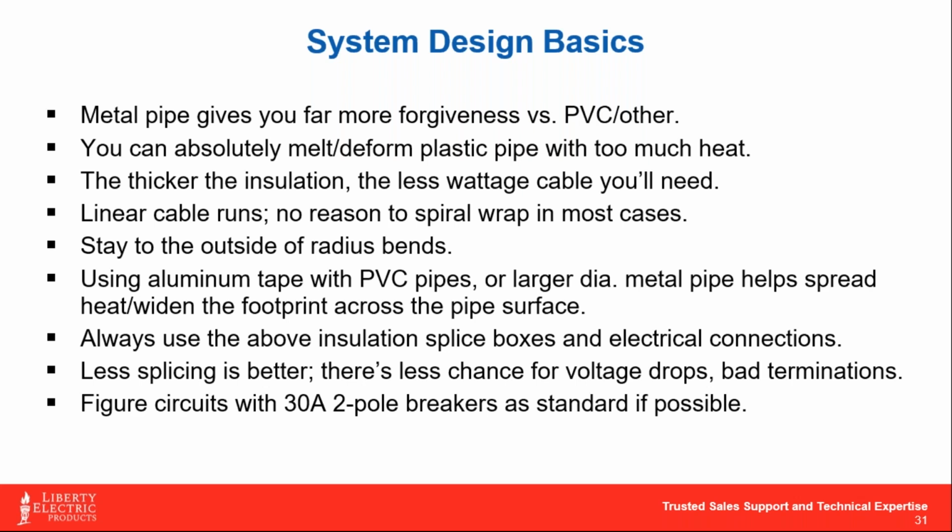Things like using aluminum tape with PVC pipes, that's a great idea. That helps dissipate that heat, helps reduce the potential threat of having a hot spot, or something where you could have a potential for melting. And the other thing that aluminum tape does really well is when we're talking about larger diameter pipes, let's say something like a 12-inch pipe, be it steel, it really doesn't matter what the material of it is.